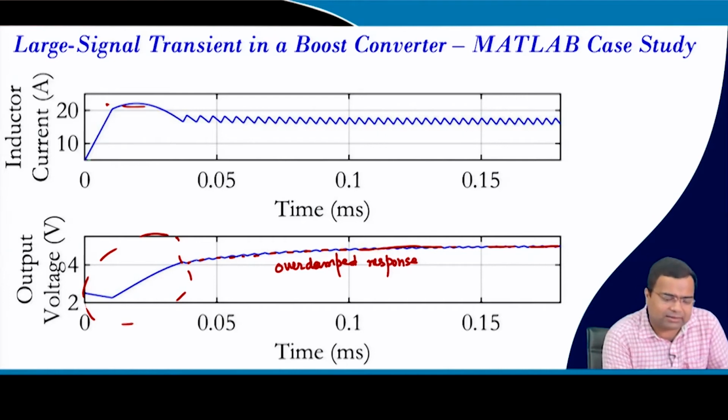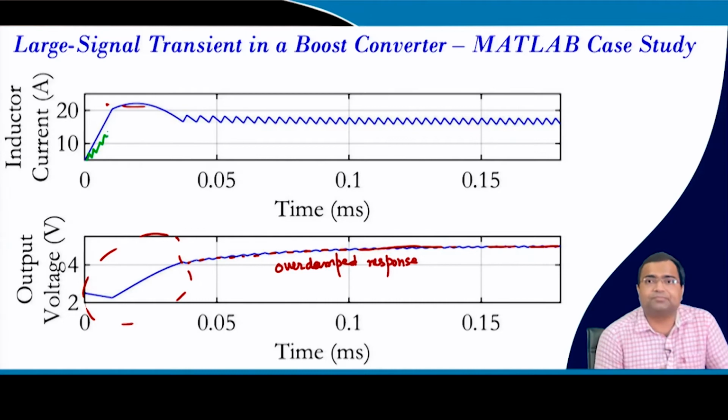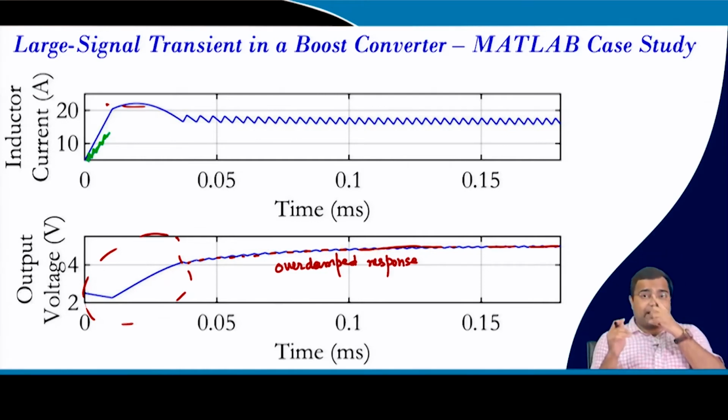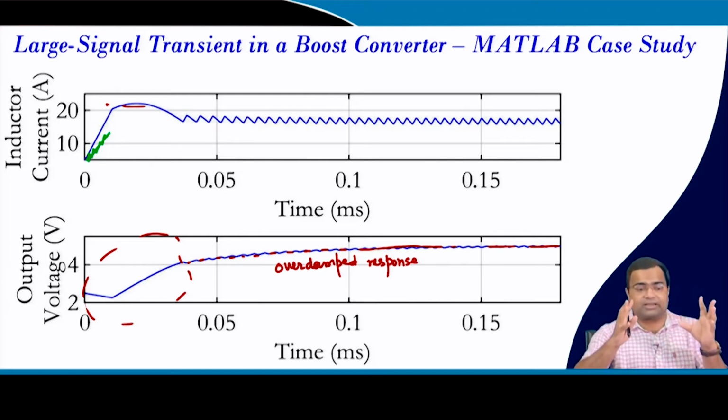But if you start raising the voltage slowly, because you may not get off operation, because your voltage is starting from 0. So, it will raise. So, you need to be very careful about the operation of the boost converter, right. Because your reference voltage initially inductor voltage is high, but the output voltage is very low. So, you need to slowly rise. So, you need to consider a special startup circuit. So, that is very important for a boost converter.